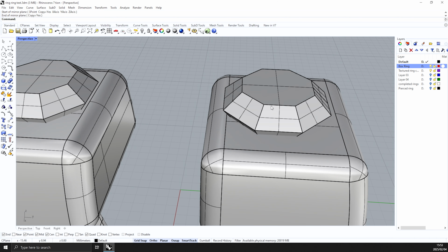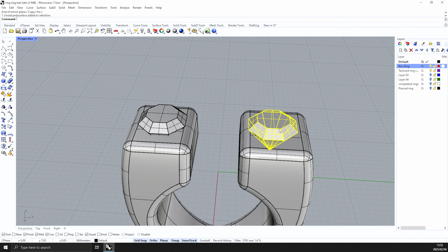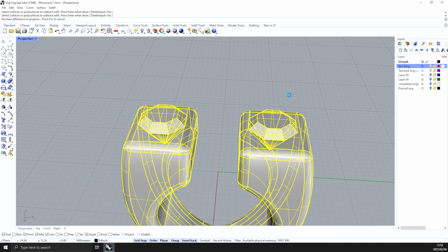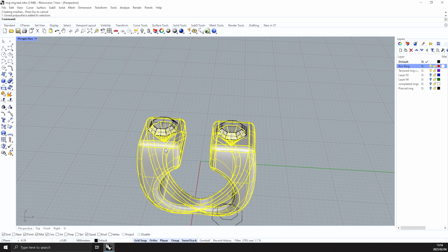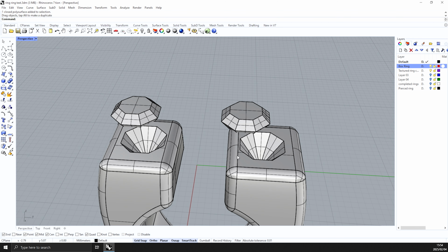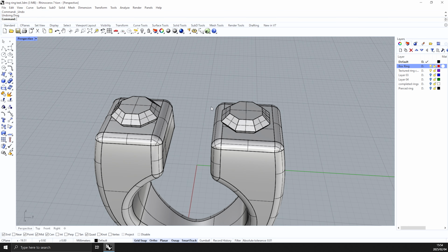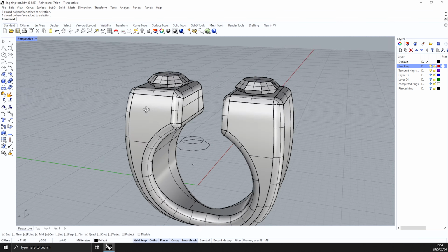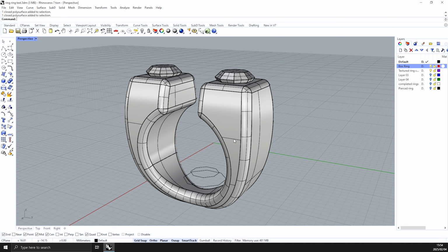And now obviously I need to create a cavity in that. So I'm going to select this guy and just make a copy. Copy and paste. I'm going to say Boolean difference. Keep this guy cut with one of those, and be okay with it. So now you can see I've created the little indents for those, but I also have my little diamond shapes to fit inside of that. So that's one way of creating a box ring, another alternative ring.